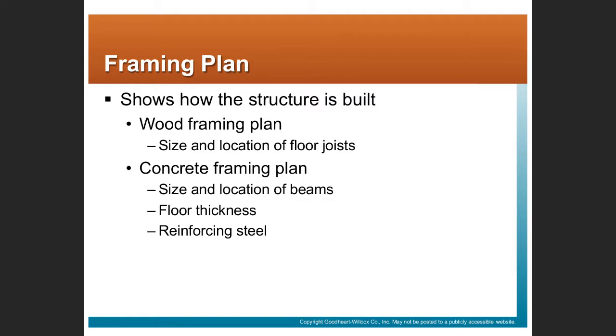Right, so the concrete framing plan will have details of the thicknesses and the reinforcement that's called for in various locations. The framing plan might have a schedule, or there might be a schedule in the specifications that shows the different concrete mix that's used in different areas.